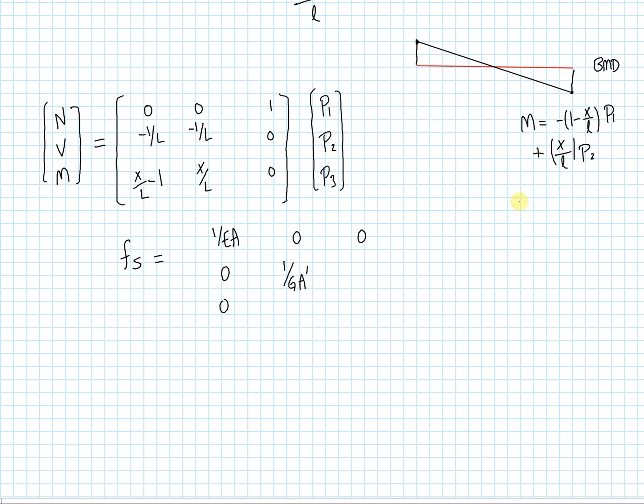So typically when we have a beam, like an I-beam, most of the shear force is carried by the area here in the middle. These locations don't really contribute much. So if you were calculating the A prime, this is what you would be looking at. Whereas A would be the entire area.